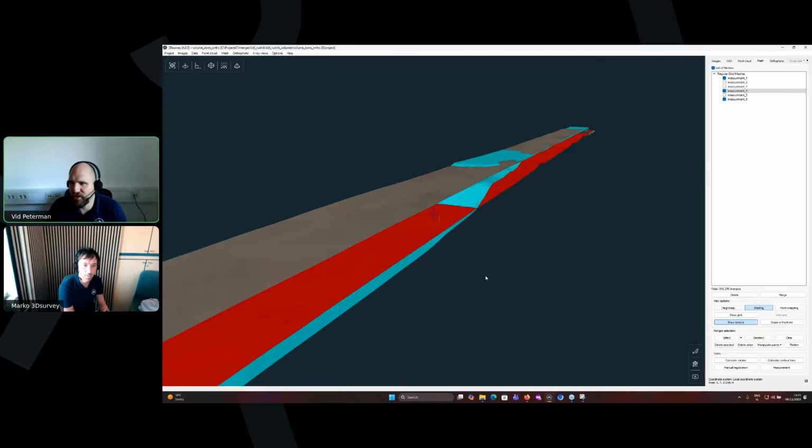Typically with photogrammetry, we can achieve vertical accuracy for the point clouds better than 2 centimeters. So if we have 2 measurements, each with 2 centimeters, then we can make an educated guess that the height difference between the two surfaces will probably be better than 3 centimeters, based on the twice 2 centimeter accuracy for each.